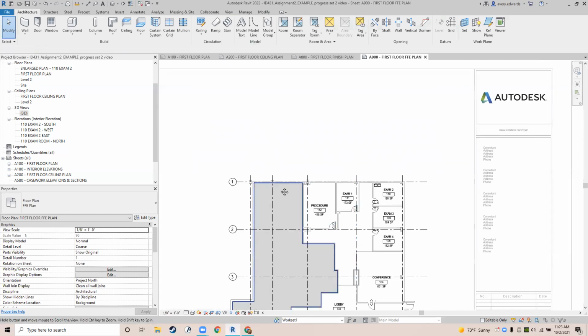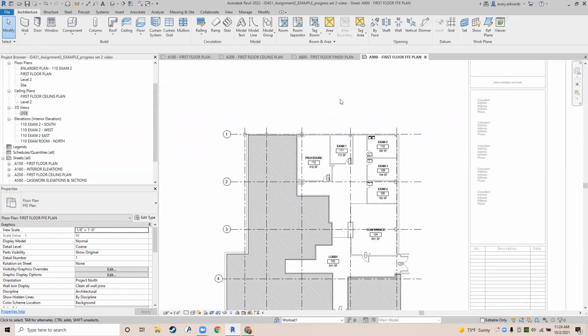We're going to do the same thing for finishes. So as you're placing your furniture in your exam room, whichever exam room you've chosen to use, make sure that you are continuing to assign that stuff to your FF&E plan, and you will know if you've missed anything, because as you go to work on other sheets, you'll see those items there and you shouldn't be seeing them. Furniture only lives on the FF&E plan. However, things that are installed like casework and sinks, if it's attached, then it's going to live on your floor plan, because anything that's attached is considered construction.